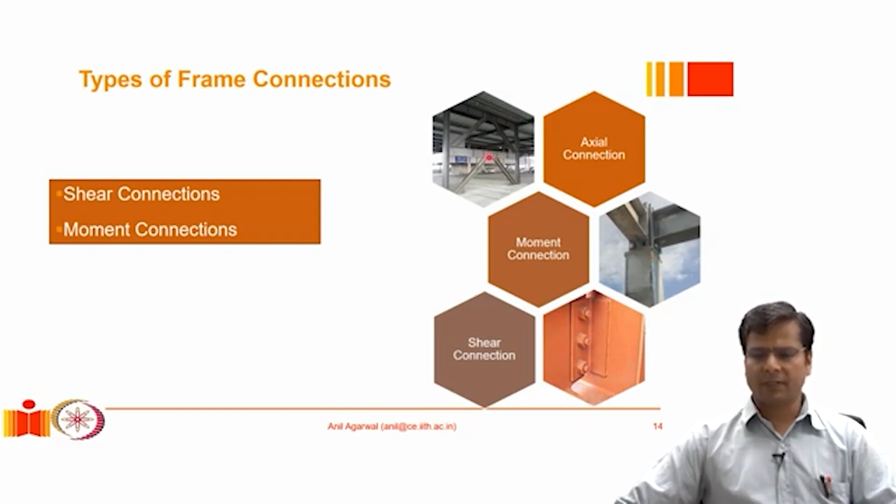In a typical steel building which has such frames to resist lateral load, such as braced frames and moment resisting frames, in addition to these 2 types, a majority of the other frames are designed to resist only the gravity loads. Such frames typically do not have a very high lateral load resistance, because the design and construction of frames which can resist lateral loads is specialized. It takes a lot of effort, time and cost.